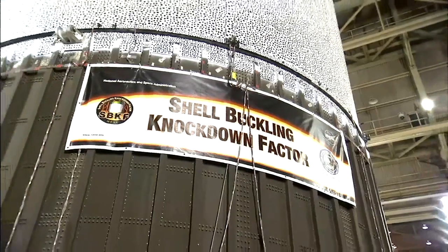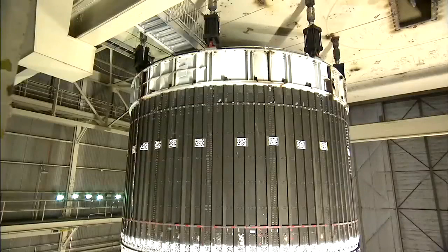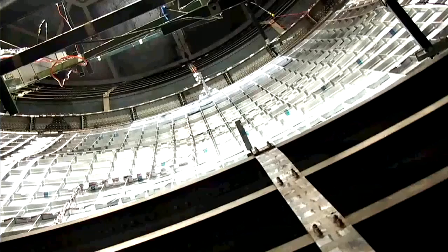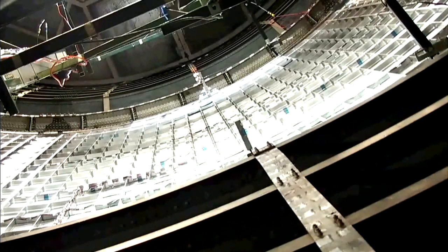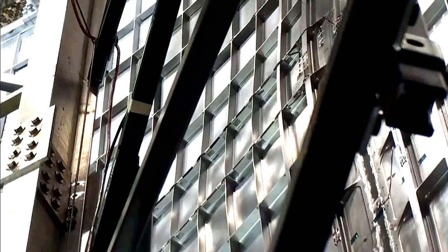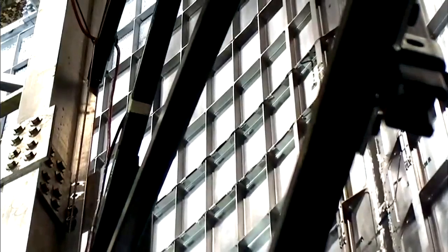The shell buckling test has been conducted at Marshall Space Flight Center because inside of our load test annex we've got one of the largest tensile test machines in the world. We've got a movable crosshead that weighs 3 million pounds and can react 30 million pounds of axial compression, making it perfect to do large-scale structural tests. It's an indoor facility, which makes it ideal for the video image correlation systems that we use to monitor real-time strain distributions during actual load events.